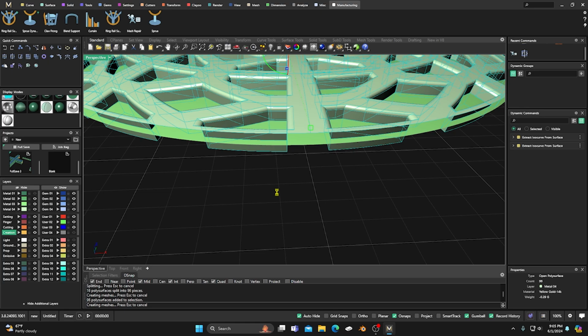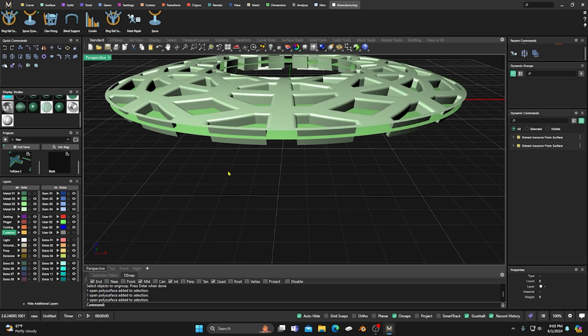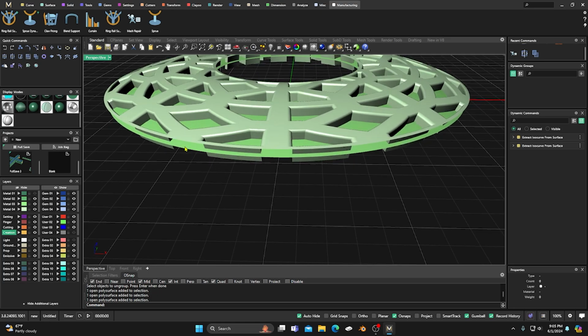And if I click on it, it selects it all again, but because it's all grouped together, if I ungroup it, you'll see that these pieces down here are all split, right? So before I go ahead and get rid of those, let's go ahead and select this surface, and we'll split it with all of this white here, and then hit enter. And just wait for it to do its deal. It could take a little time because we split all those. So it's going to go through and split all that.